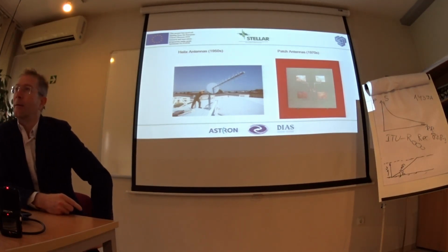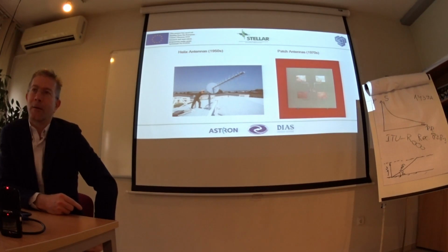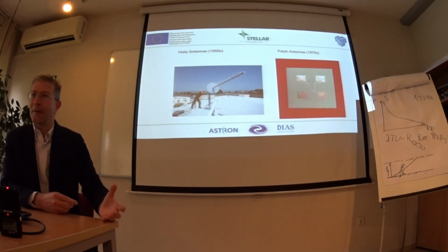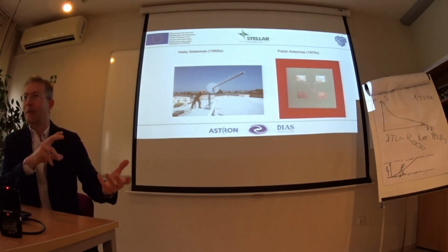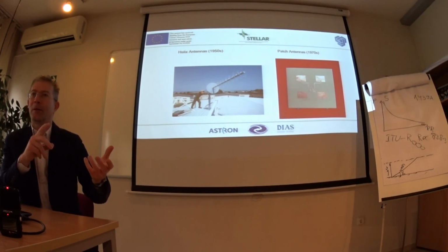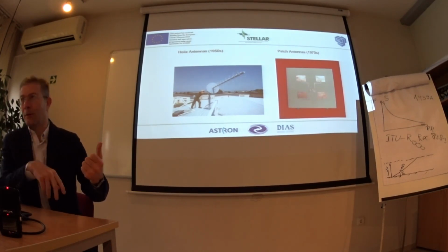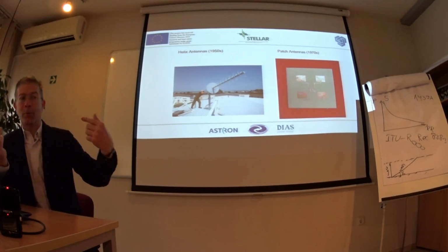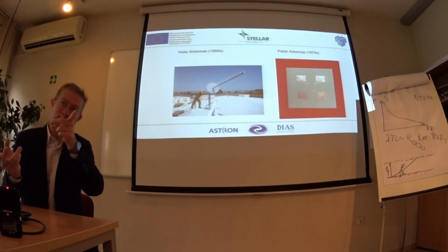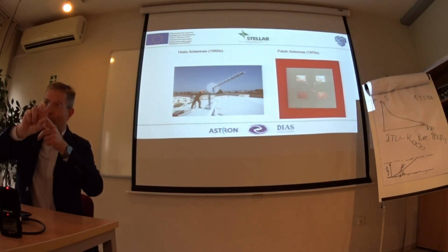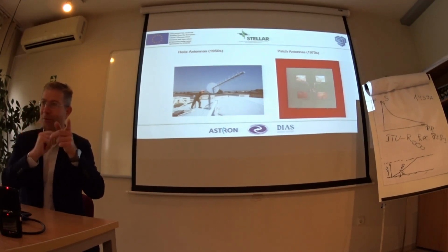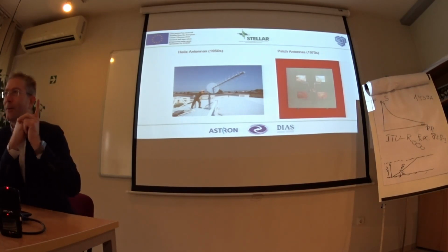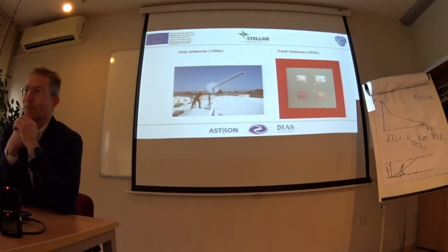And this was a great problem with the first satellite. The American team mistook the sense of polarization, so they couldn't receive the signals from the satellites. Fortunately, the British were aware that if you look toward the antenna or from behind the antenna, this changes the sense of polarization, so they did it right. They were able to receive the signals from the satellite.